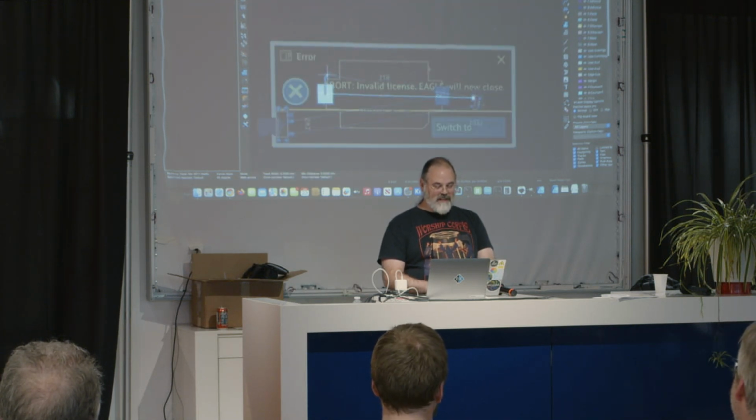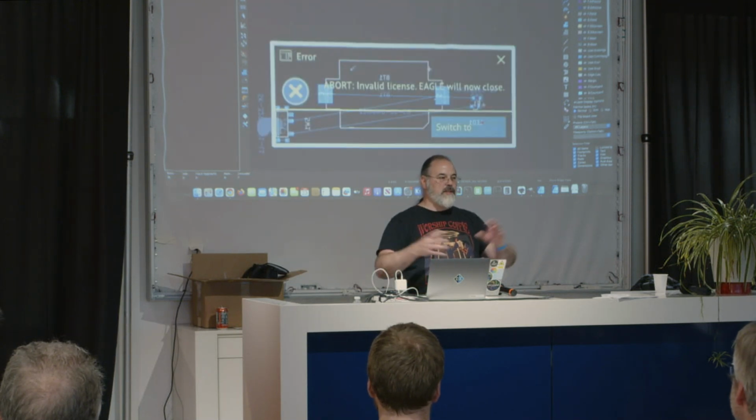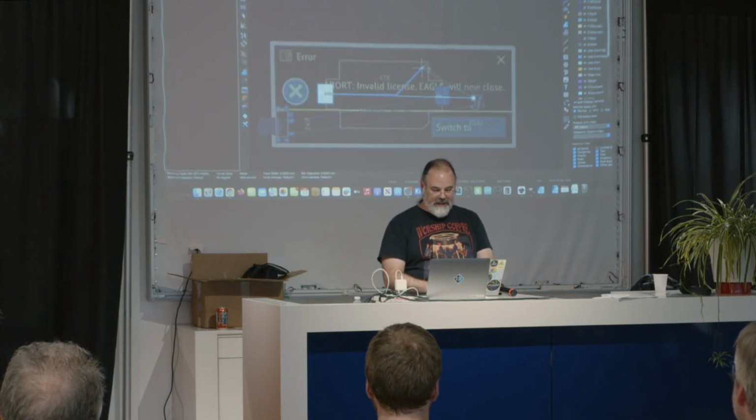So I'm just hitting X. X is going to start drawing some wires. I could go through and define net classes of minimum widths and all that kind of stuff if I've got power signals and all that. For this little low current stuff, I'm just going to not bother with that. Let's drag this over here. And you see I've got these nice 45-degree angle lines.